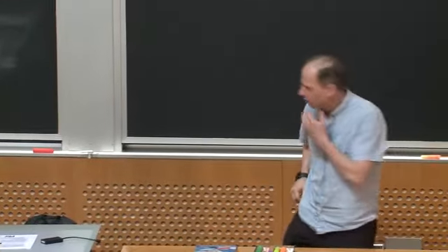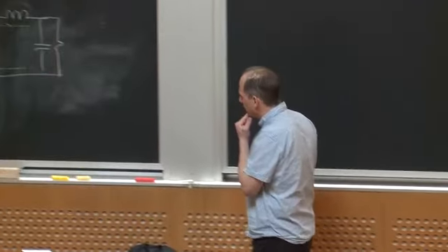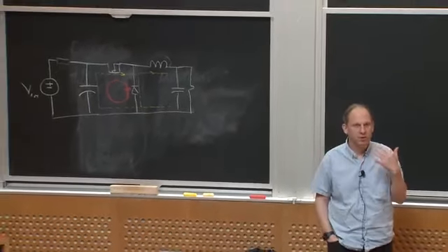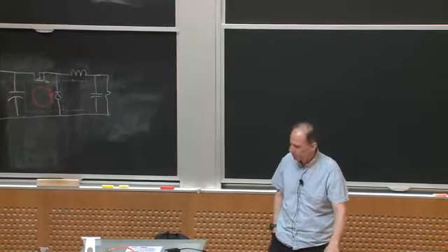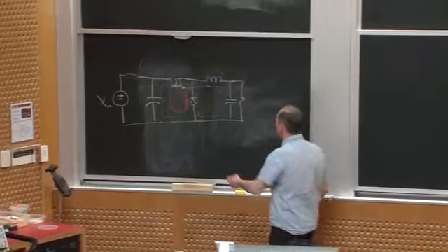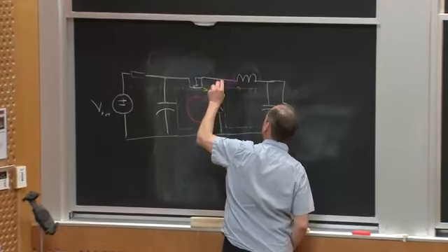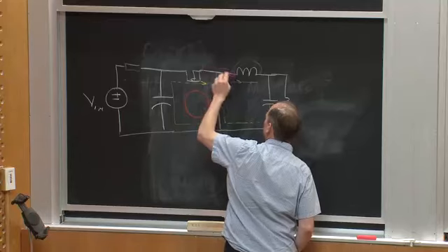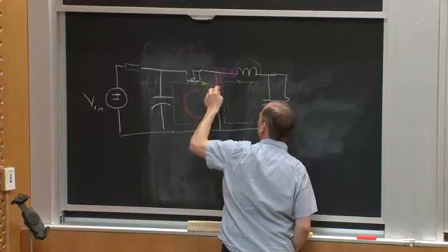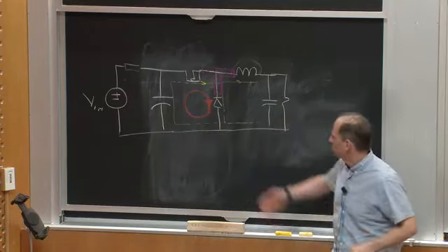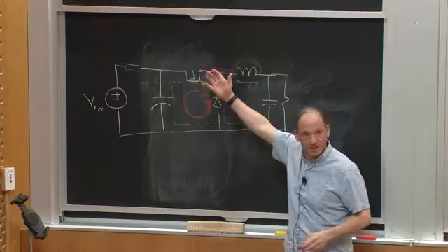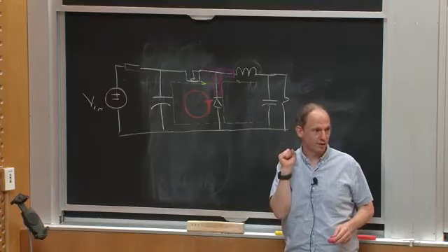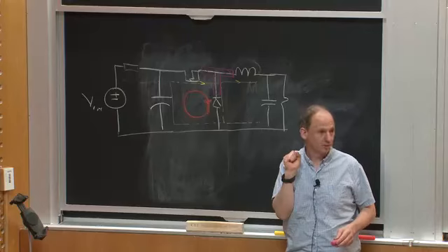We should also recognize where the high switching node is in this circuit. This node has a big square wave on it with respect to ground. So this node flying up and down can inject charge into other places in the circuit and cause noise.